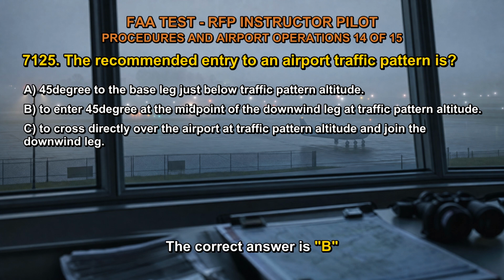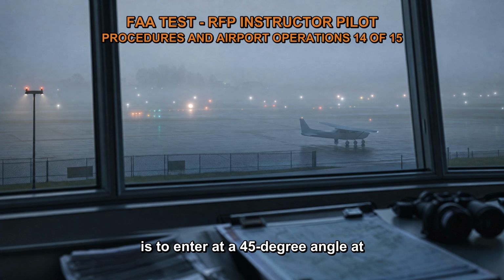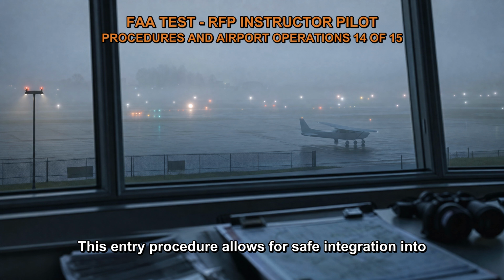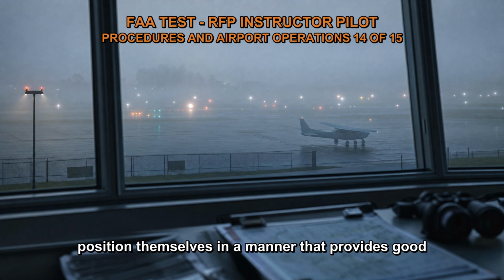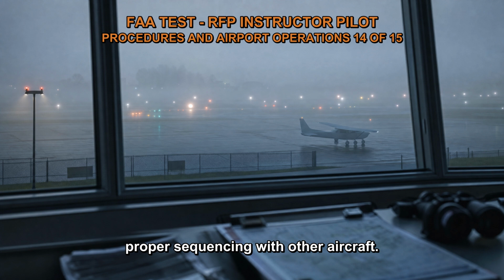The correct answer is B. The recommended entry to an airport traffic pattern is to enter at a 45-degree angle at the midpoint of the downwind leg while maintaining the traffic pattern altitude. This entry procedure allows for safe integration into the existing traffic flow and minimizes the risk of conflicts with other aircraft. By entering at a 45-degree angle, pilots can position themselves in a manner that provides good visibility of the traffic pattern and allows for proper sequencing with other aircraft.